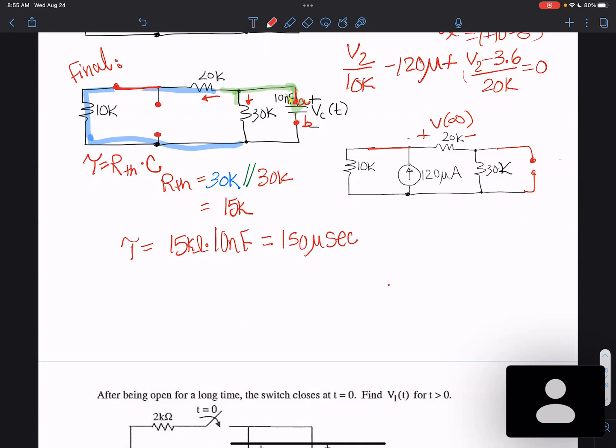Okay, if we knew the voltage here, we could do a voltage divider. You could also do a current divider and then just use the current and do I times R there. So that would be another way. Any other thoughts? How else could you solve this?